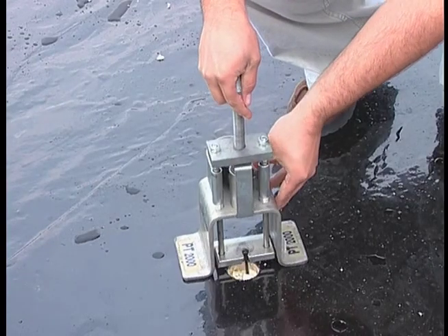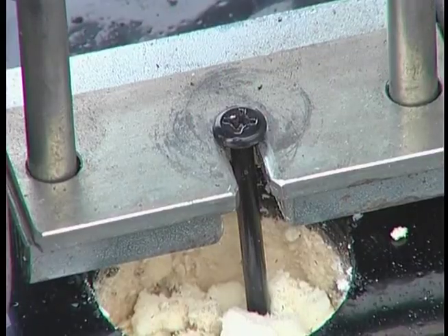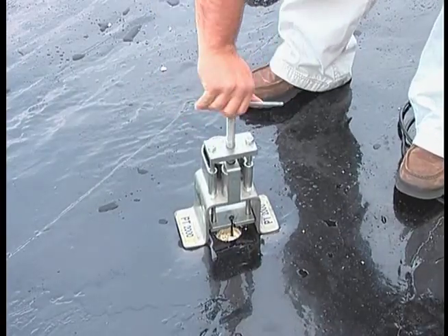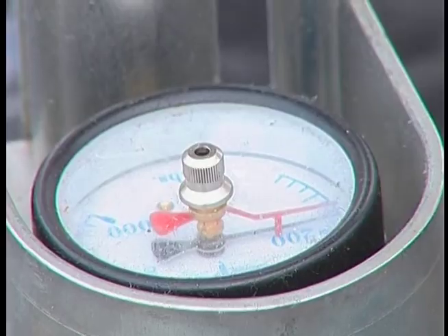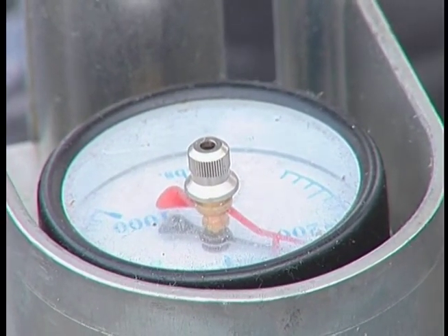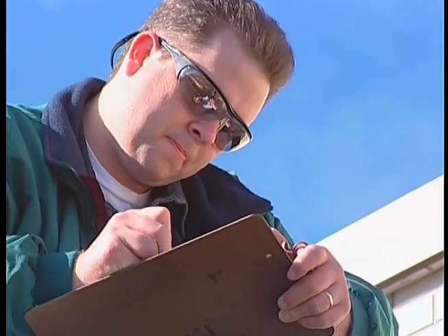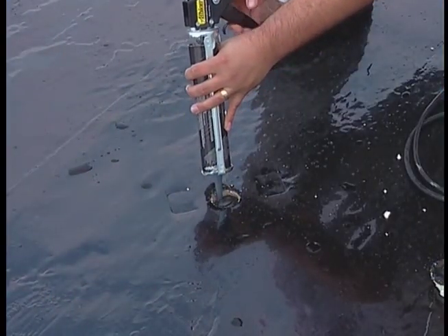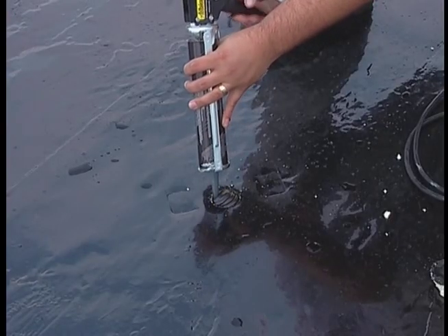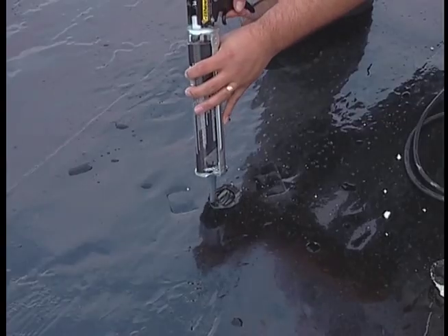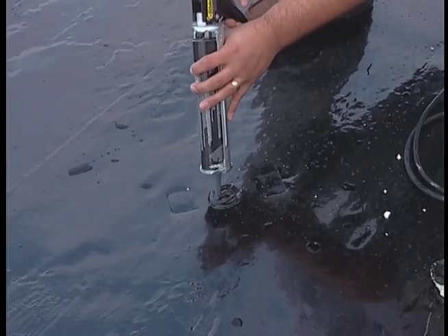Attach the pull-out tester head plate under the head of the fastener and twist the handle until the fastener pops out of the roof deck, observing the pull-out tester gauge to read how many pounds of force are required to pull out the fastener. Record this data in writing and keep it. After the pull-out test process is complete and you have gathered all the needed information, make sure that you do all the needed repairs to ensure that the existing roof is watertight.